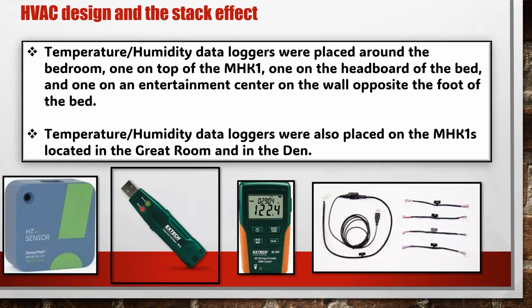Yeah. If you cut it, it's a one-way street. You're not going backwards again without replacing the board. And they're using the MHK2 with that cut. Does that help? Not necessarily, no. The only thing the MHK2 helps you with is showing a more accurate reading of the room temperature, not being influenced by the heat from the coil. That's the only advantage you really gain there.